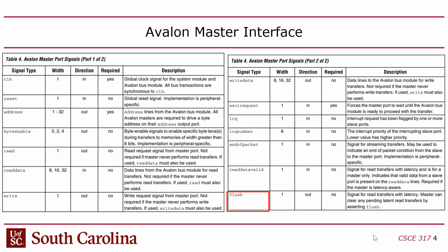It's kind of like we talked about in I2C, there's a similar feature called clock dragging? I forget what it's called now. What is it? But basically, in I2C, the slave can hold the I2C clock down, and that gives it more time to be able to respond to the read. I can't remember the name of it now. Clock dragging, clock stretching. Yeah, but in this case, the wait request is used for that purpose.